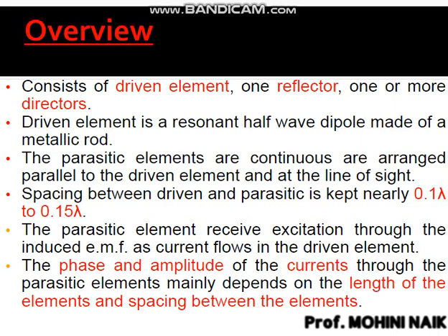So for all these cases, if I design an antenna and test it, first simulate it, because simulation will give me results much in advance of fabrication. Fabrication is simply a waste of money and time and resources as well. So simulation will tell me which one will give me a better result, and after this analysis I can easily see that the 0.15 is giving me a better result, so I will keep the distance as 0.15 lambda. So this is what the designers do. They try and test and simulate, and only then go for fabrication.